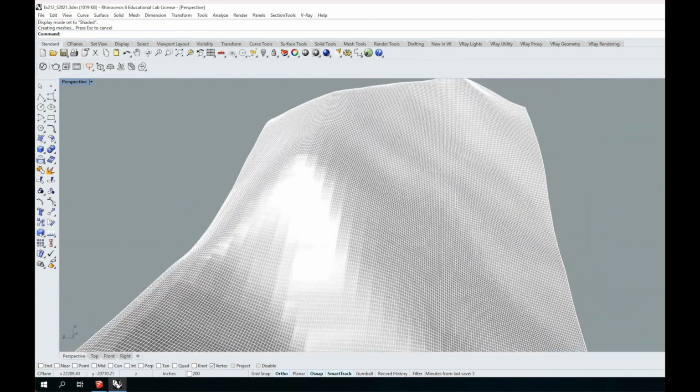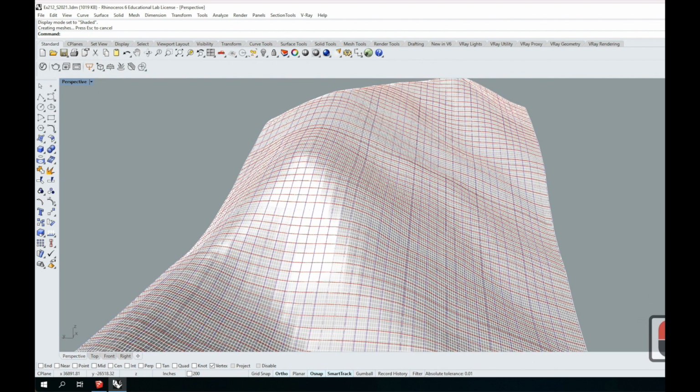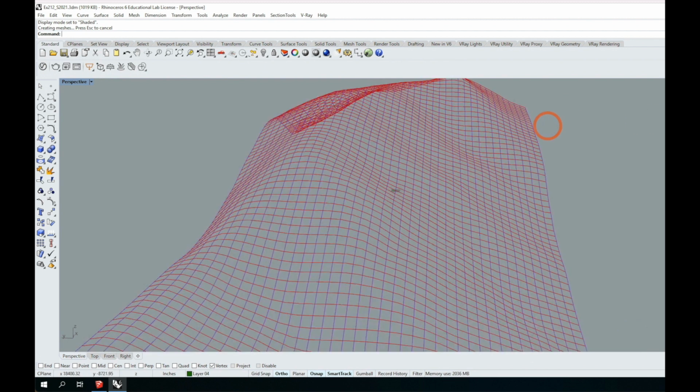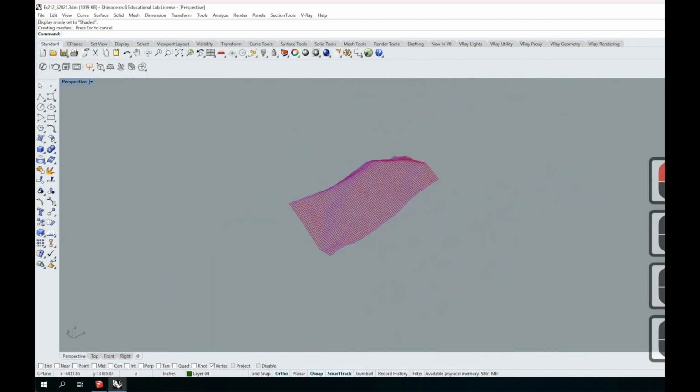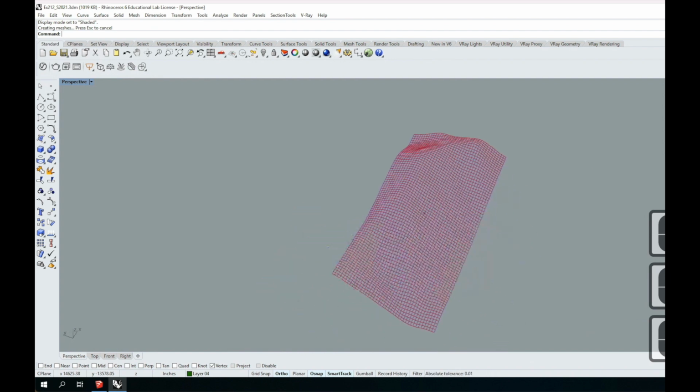And I'm going to process this again. Now you guys, for exercise 212 here, don't need to reprocess this each time. You can just rebuild the same surface. But for my purposes and the instructional purposes, I'm going to go ahead and rebuild this again. So let me make layer 4 active. And I have contour X and contour Y turned on. I'm going to turn off contour 200. And I'm going to do that network surface again. This time I'm going to show you with less curves.